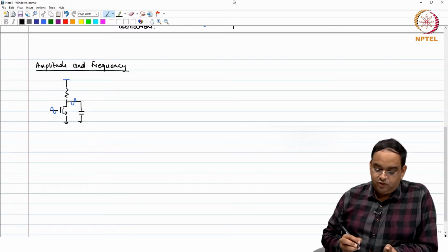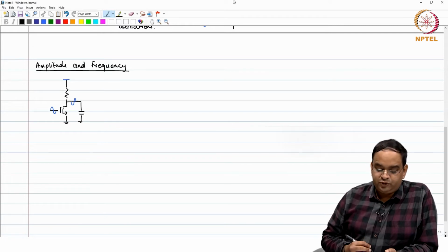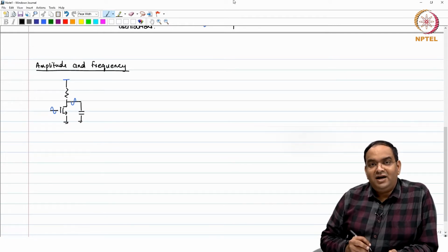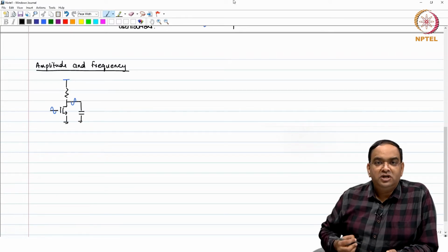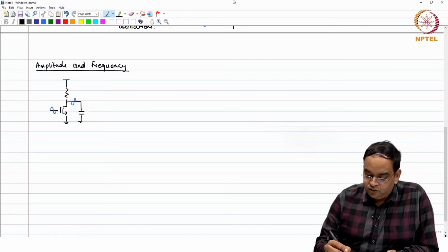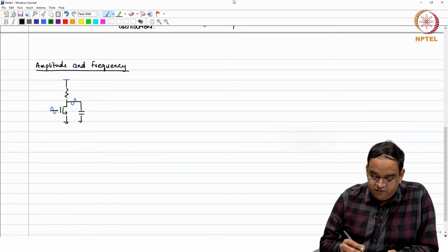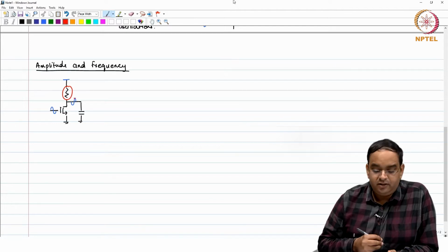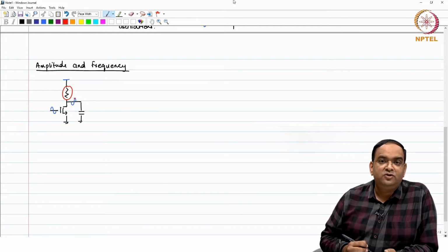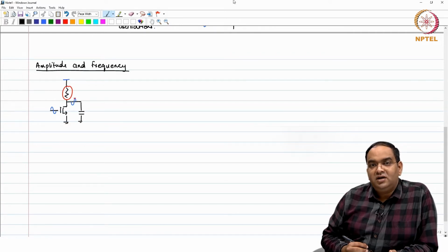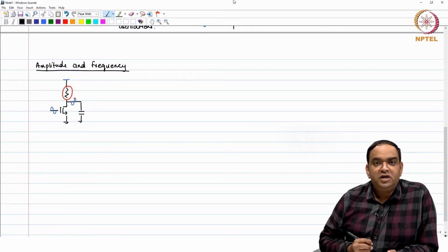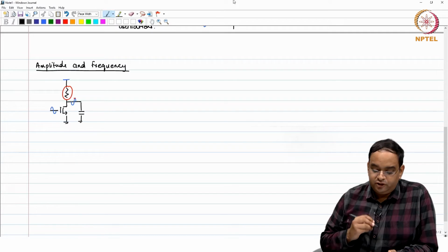Okay. So, if we would like to control the output swing, we would like to have a fixed current going through the resistor. Okay. So, fixed current, because the swing which you are producing at the output, when you have a maximum swing here, that time you are having maximum current going through the resistance. So, if we can control the current in the RC load, then we can control the output swing.